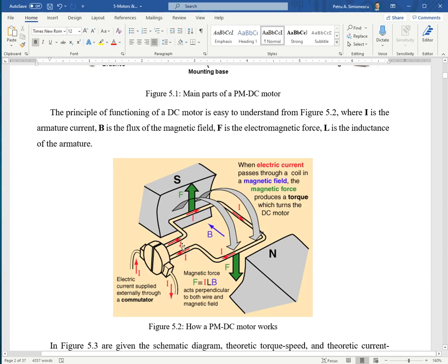Now, a motor of this design will not be able to self-start, but it will run. If you fabricate it, it's missing the rotor, but you can introduce a shaft supported on two bearings. The commutator has only two blades, and then you have the brushes seen here. So you can have this run as a motor, pretty inefficient and not self-starting. In order to start it, you need to give it a kick, and once it reaches the desired speed, it will continue to rotate.